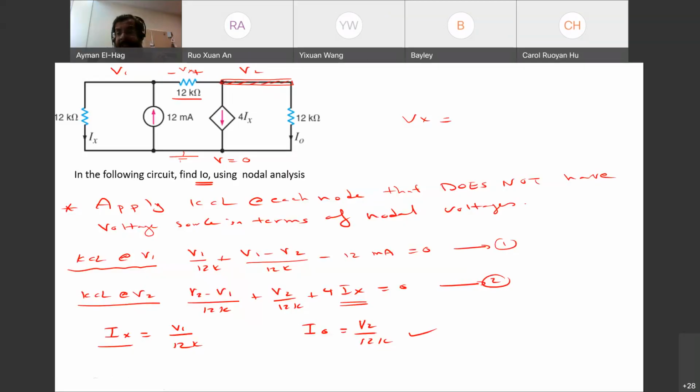So as you can see, with nodal analysis, once you find the nodal voltages, you have solved 90% of the problem. Then, once you know the nodal voltages, let's see what exactly is requested in the question, and you can find that easily. Basically, you will apply mainly Ohm's law. Or apply a simple, it's not KVL actually, but it is a sort of KVL. When you say V2 minus V1 for Vx, it is a sort of KVL, although we don't see it.